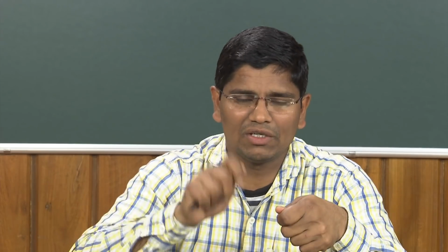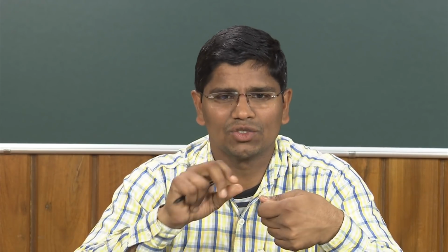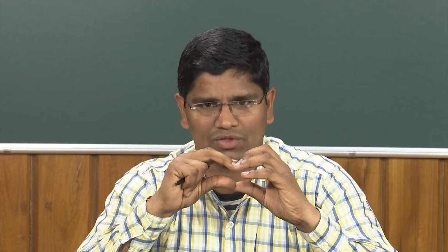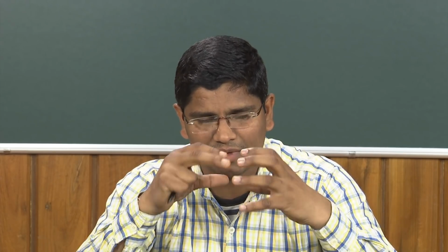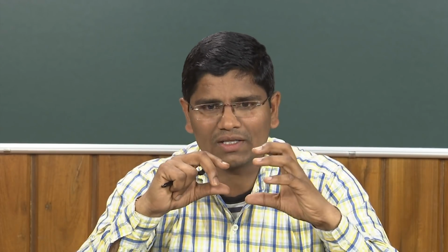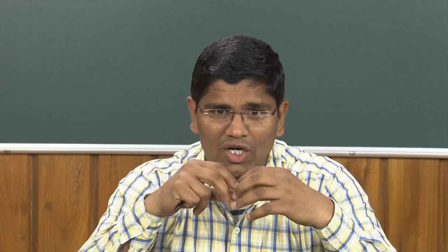Then you take it to the edge and hit it so that it becomes sharp. Then you put it into the water so that it goes back to its original microstructure. It may not be 100% the original microstructure, but it will go. So the sharpness will increase. The bottom line is that the change is microstructural, and the microstructural change is taking place because of the temperature.